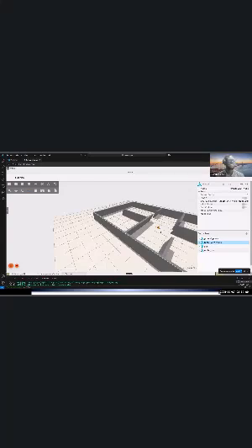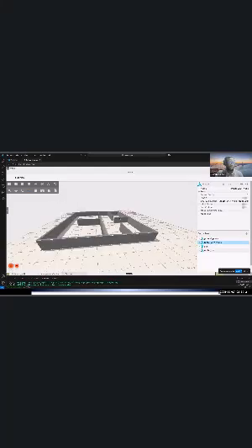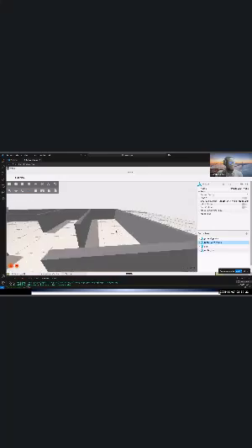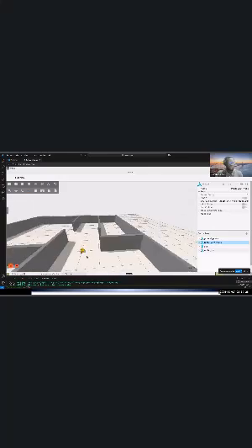In hardware, you most likely will not use Gazebo, but you will most likely use RViz because you need to visualize, see the sensors, get the data, and mix the sensors, right? So now you see what the robot looks like in the world. It's a big room with walls. The robot is just there, it's not doing anything yet. I'm going to open RViz so you see what RViz looks like.